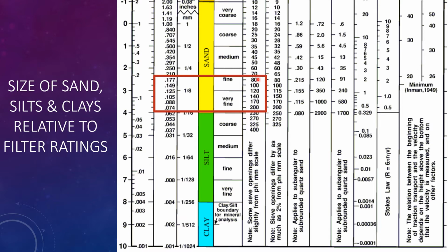And you'll see an example of the separator working in Kansas where they had an 80 mesh filter, which is basically a 177 micron filter, and that basically was being overloaded every day. You can see for tapes we might have a 200 mesh filter, which would do the 74 micron. And so all of these solids below 74 micron are typically not addressed by filter systems or solutions offered by the industry. And so it's quite important what we're doing, because not only do these plague the filter, but they get through the filter and impact the system negatively.